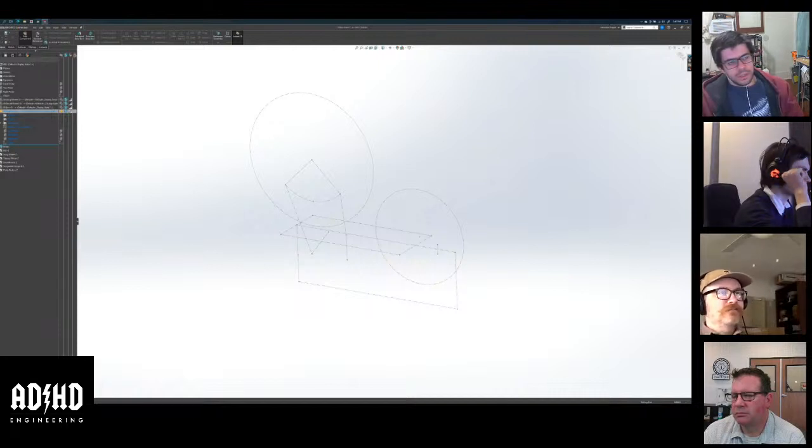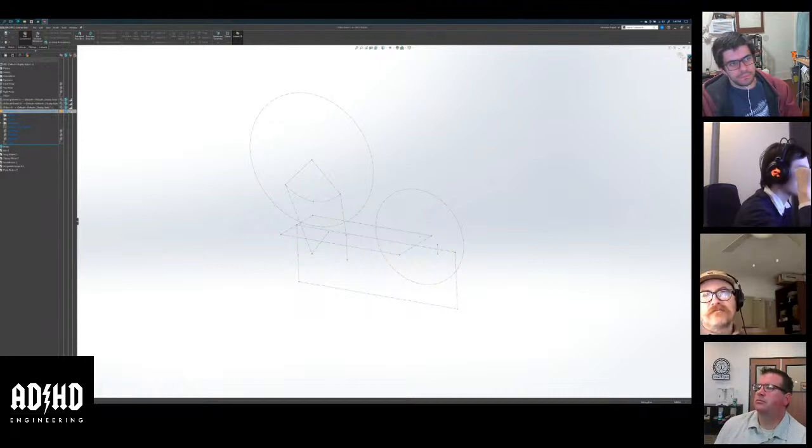The other thing is having the skeleton means you have reference geometry that you can assign to those origins in the parts. So again, there are arguments for it, which I like. There are also arguments against it, but if you really want my vote, I say every part should probably have its own origin.